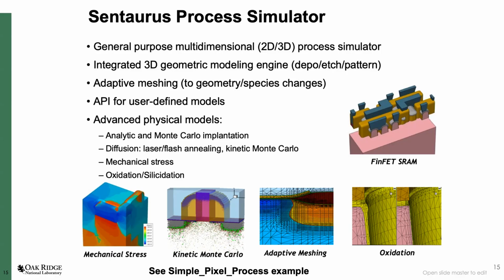There are even APIs, in Python or in C++, so you can, if you're doing really detailed device physics, or for people that are working with different materials that are not silicon. I've seen people trying to do things with germanium or with heterojunctions or diamond. So there are a lot of data sets for a lot of materials in there, but you can also implement your own, let's say, impact ionization model, or your own implantation depth versus energy model or something like that. An advanced feature, but it's possible.